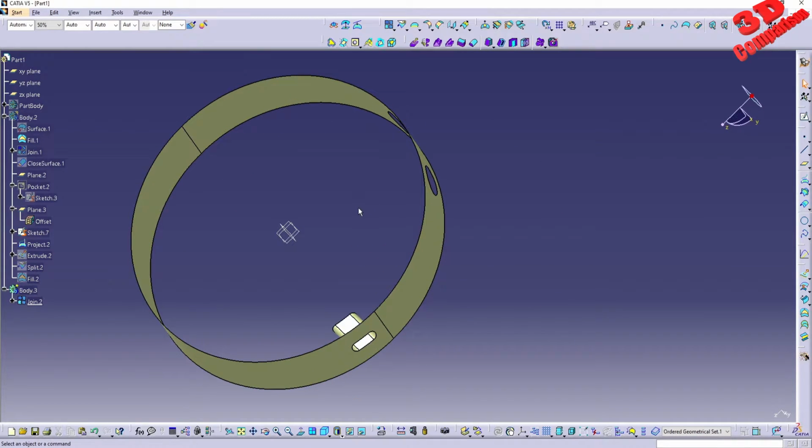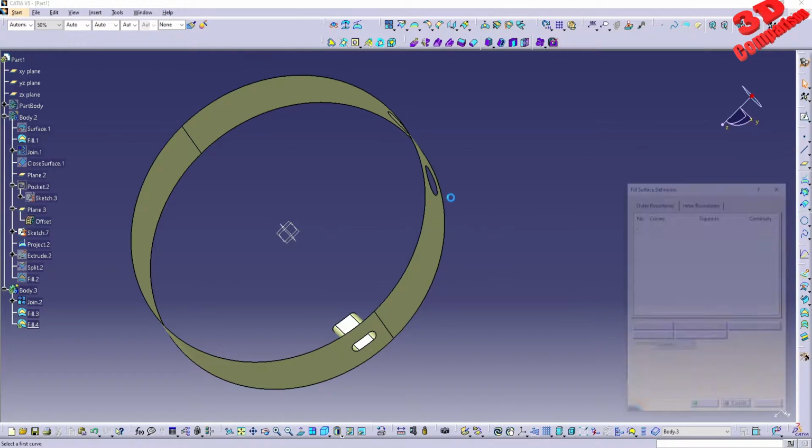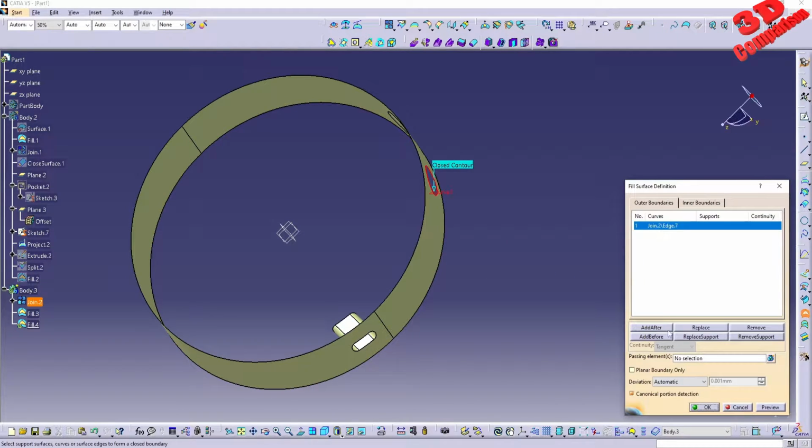Now, if I want this to be a closed part, which will be, let's say, easier to work with within part design and most common, I have the possibility to go and fill those as well. They will each have to be filled individually, so you cannot add multiple closed sections over there.